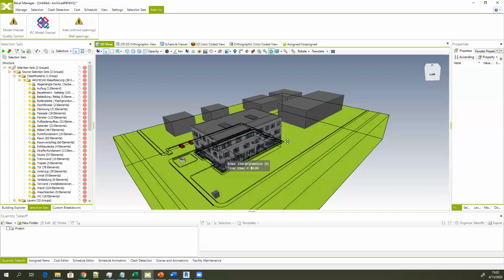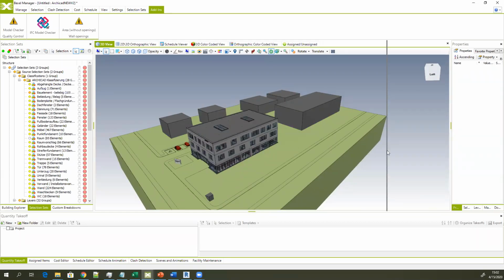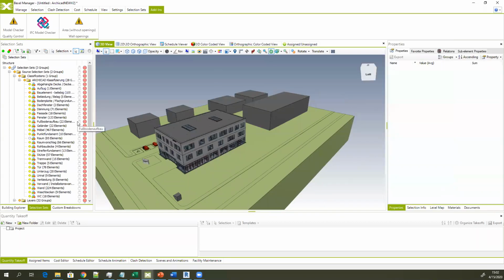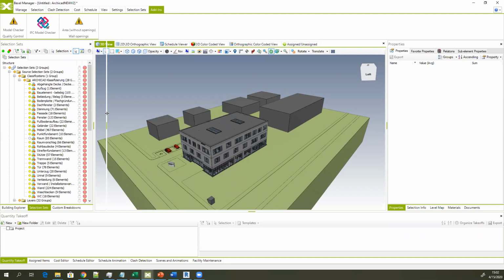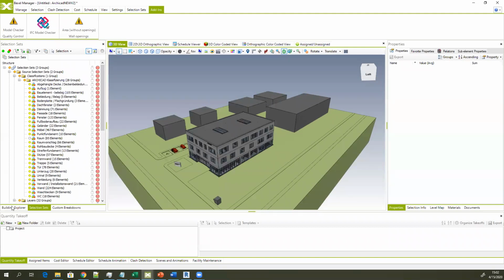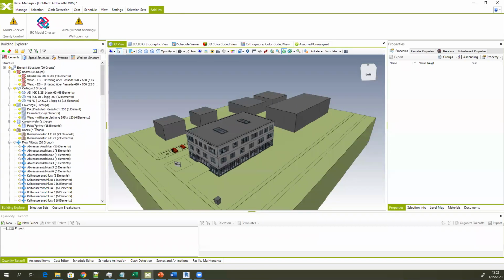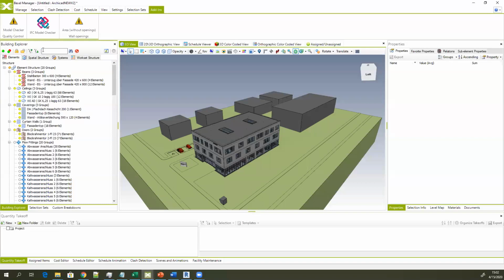So in this case, we have a new BIM model, which is also created from IFC files. Also, I forgot to mention, but this is something that is commonly done, and you can find this information within the manuals. So for all these segregation elements and segregation methods, you can search for specific types of elements using the filtering option.